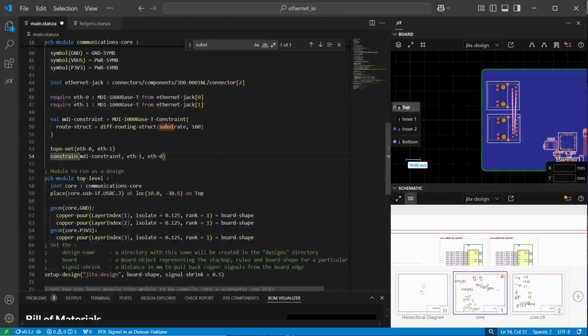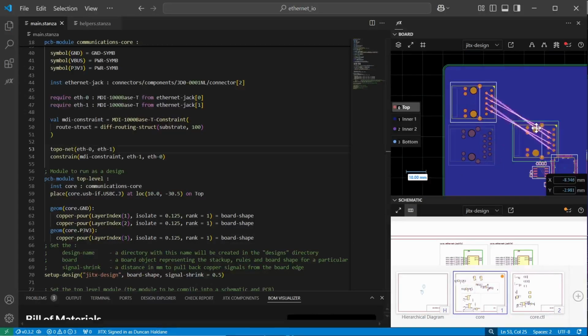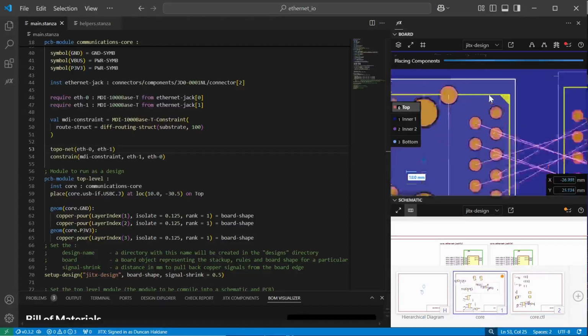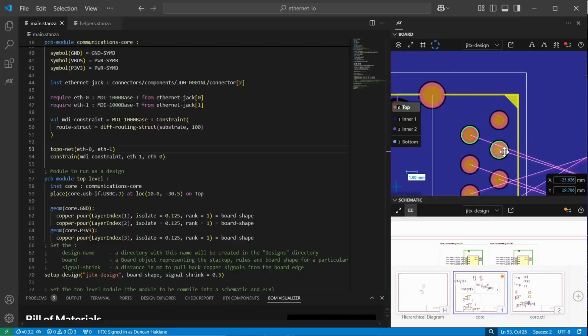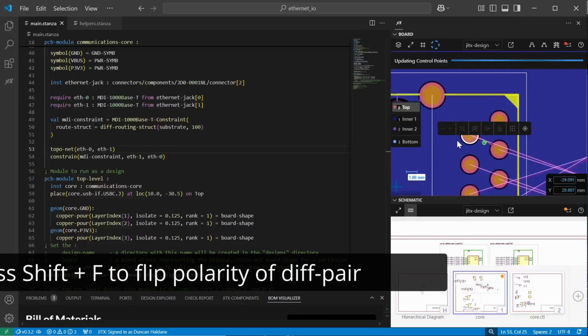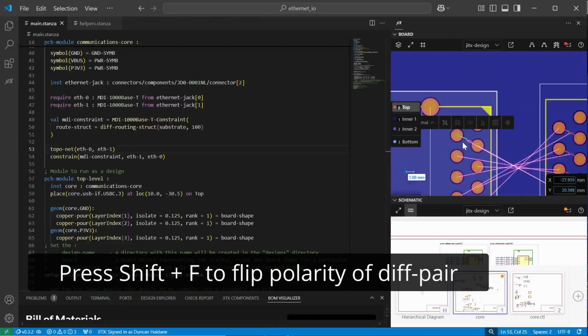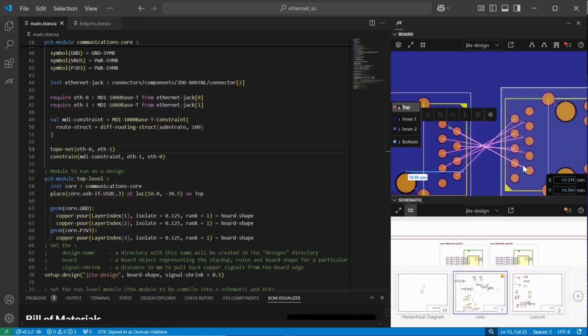Instead of looking these requirements up and manually mapping the constraints to net names in every design, you just use the shared library to automate and standardize your practices. And of course, you can get in there and tweak those numbers if you want. Save and run this. Okay, and let's demonstrate our new structure here. So we add a routing point back in, and we'll have to flip it so that it connects. And select those two and route it.